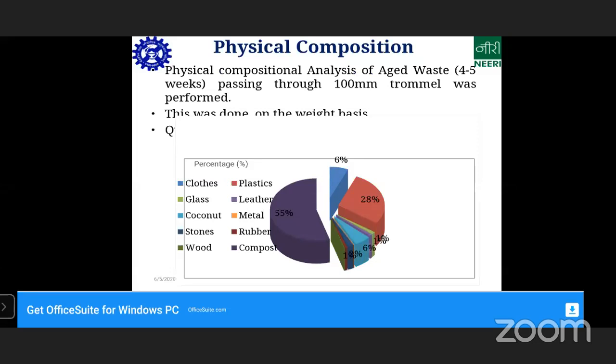Other things are usually mixed, and they send it to a segregating unit. The segregating unit usually contains a trommel facility, which will segregate the smaller particles: 100 trommel, then 75, then 35, then 16, and then 4. Whatever passes through 4 is regarded as compost, and the rest is rejected. A trommel is nothing but a round sieve. The rejected part again goes to the landfill.